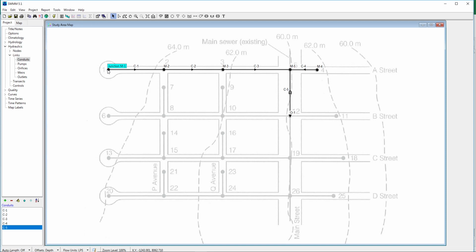Also at the manholes I have to enter the value of the inflow that has to go there. And when the inflow is there, then I have to enter the pattern as well. The pattern is given at another place, so I will bring it, and then I will show you how to enter the pattern as well.